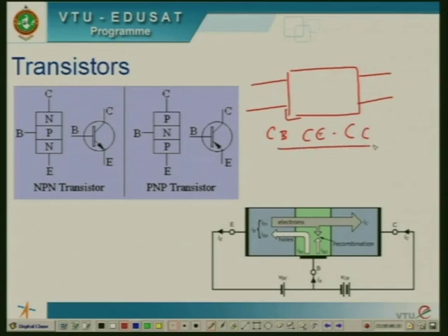There are two junctions, and as already specified, the transistor changes state from conduction to insulator. Hence the emitter-base junction, or input junction, is always forward biased and the collector-base junction is always reverse biased for proper amplification.